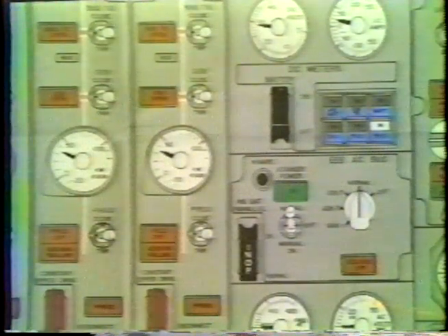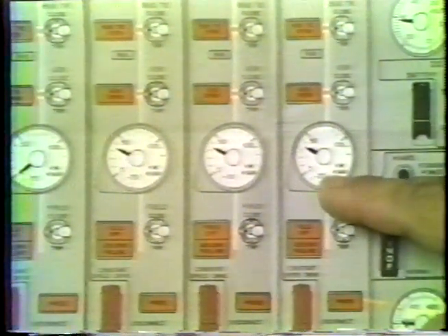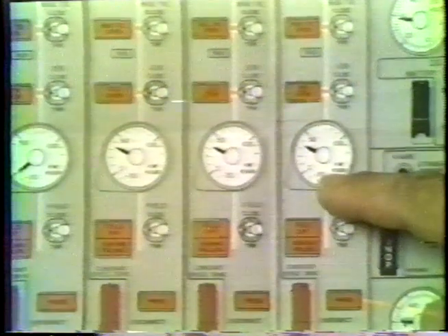The kVARs represent balance between operating generators. The value of the kVARs is not of particular importance, but when generators are operating in parallel, the balance between the highest and the lowest indicates how well the generators are operating together.